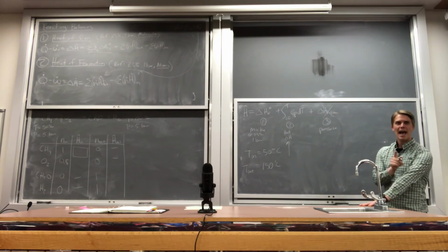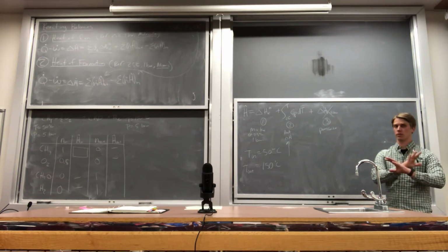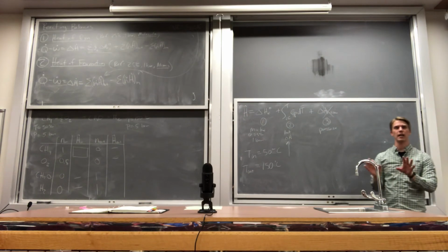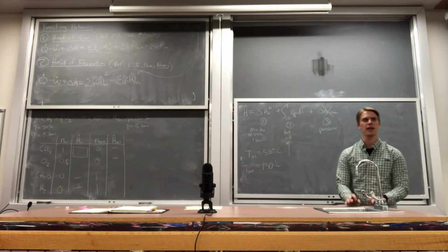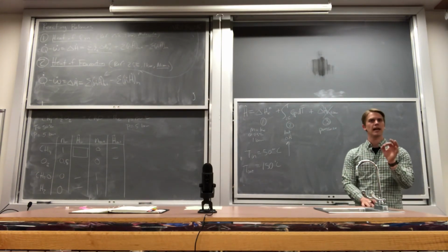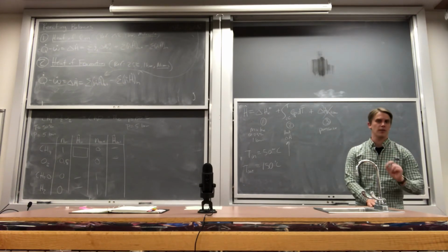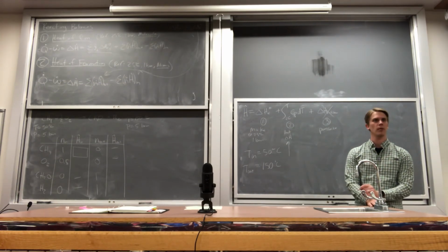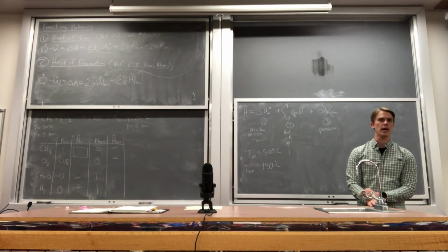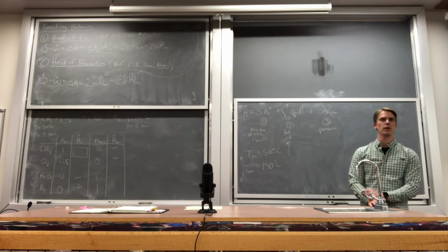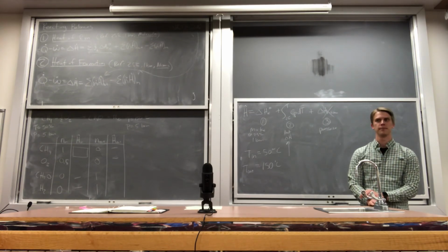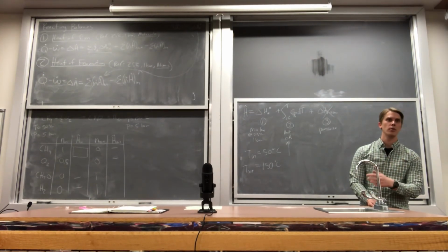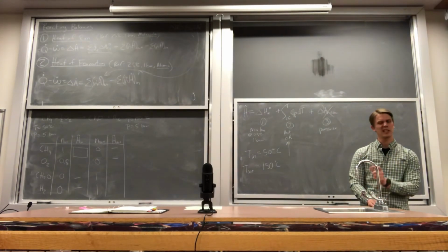So for an ideal gas, strictly speaking, other than all the ideal gas approximations, the enthalpy is not a function of pressure. For a liquid, it is. So for the liquid, we have delta PV as how we keep track of the pressure change in enthalpy. That's specifically what I was looking for in that problem, because it's 200 atmospheres, which is clearly high enough to be a relatively significant contribution to the enthalpy for pressure changes.